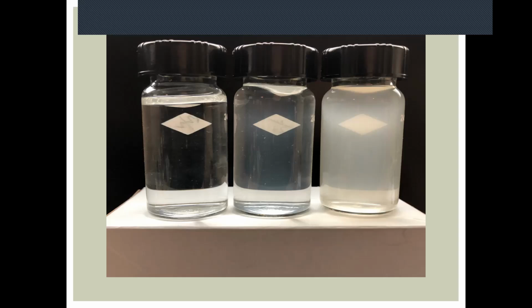The sample on the left is 1 NTU measured with a turbidity meter. So basically drinking water. The center one is 25 NTUs, which is the number that Department of Ecology uses for you're good. Anything between 0 and 25, you're good. And the one on the right is 250 NTUs. So 250 and above, you're not all right, and you have to report to our state agency.